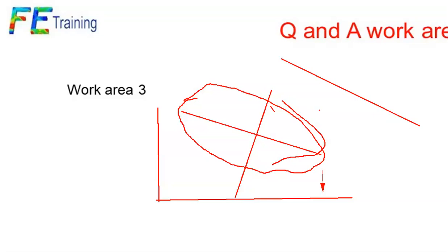That's a big question. If we've got pure shear and we actually have a shear SN curve, then we could deal with that. If we've got something which has shear and direct stress, but it's proportional, so we're just scaling that stress state up and down, that's called proportional, then we could use a signed von Mises, which we touched on briefly when we looked at the Mohr circle. We could use a signed maximum principal. What we've got there is a combined stress state.